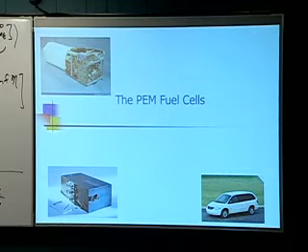And this car is getting an effective storage, if you use the super grade of sodium borohydride solution, that is, get it as close to saturation as you can deal with. That's equivalent to having a gas cylinder which is by mass giving you 7% hydrogen. Your typical steel gas cylinder that we have in our labs, it's about 2,000 psi typically, and the storage there is somewhat under 1%, to give you a feeling for this. And you don't get very much range, obviously, if that's what you're going to deal with.